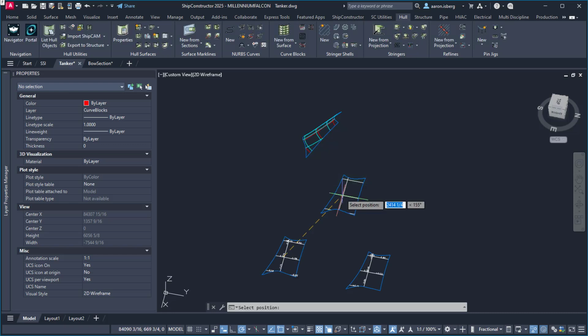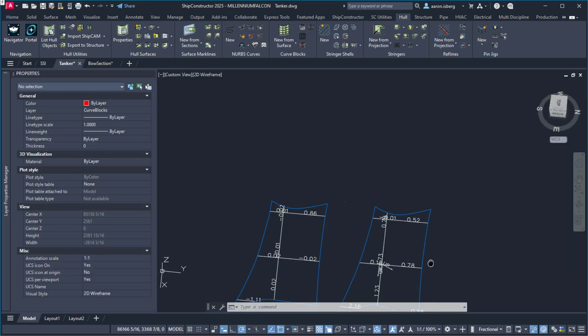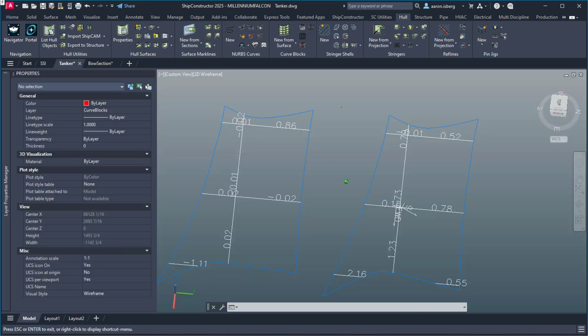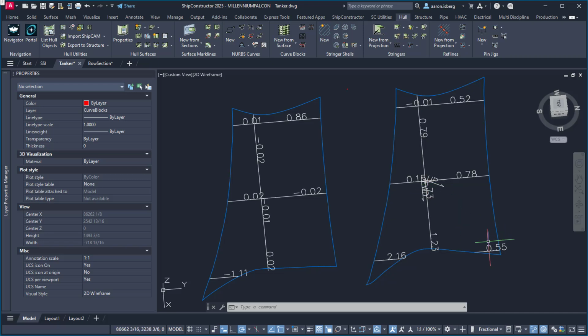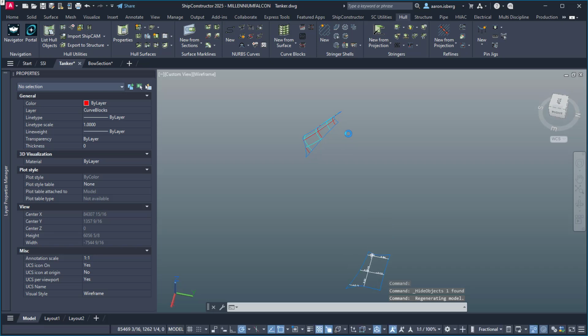Note that you cannot export both of these expanded plates to structure, as only the last one created would be a valid plate expansion object. The process of creating both here is simply to be able to view the differences in elongation values at this stage, and then to decide on which option suits the elongation process.